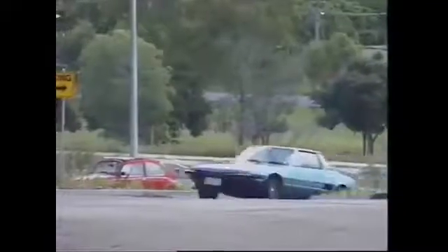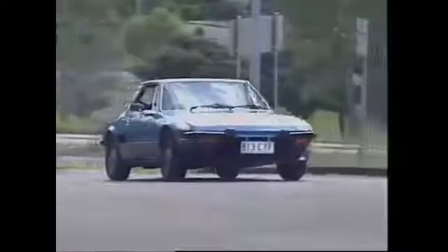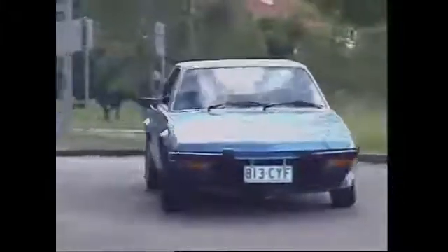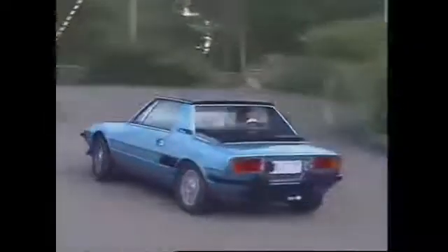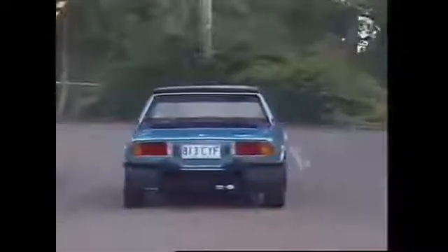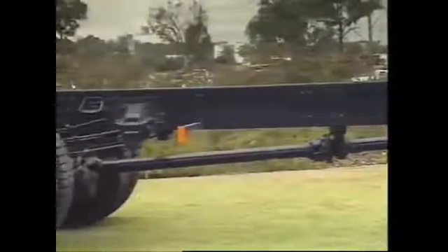A mid-engine design locates the mass of the engine behind the driver but forward of the rear axle. This allows for a low bonnet profile and good handling. Most goods-carrying rigid commercial vehicles locate the engine near the front and drive the rear axle by a 2-piece propeller shaft. The rear axle supports most of the goods or payload.